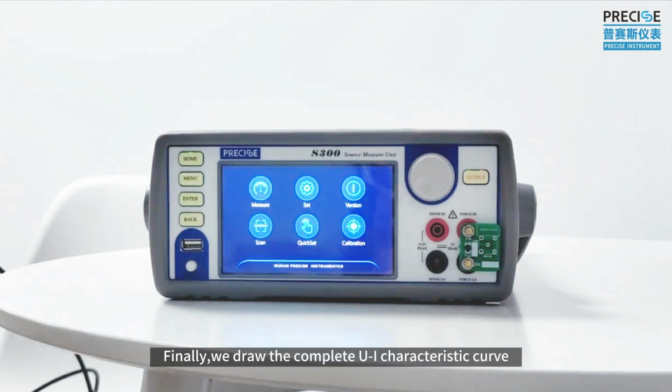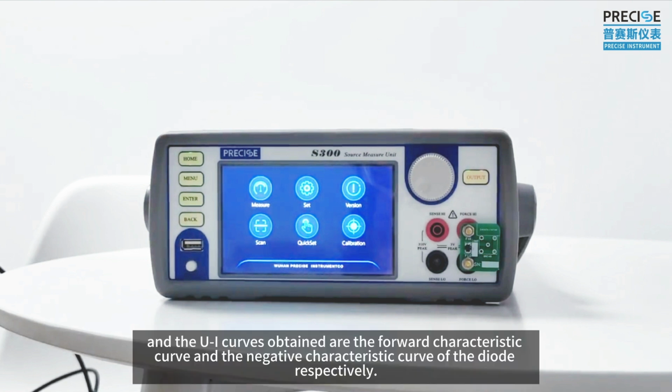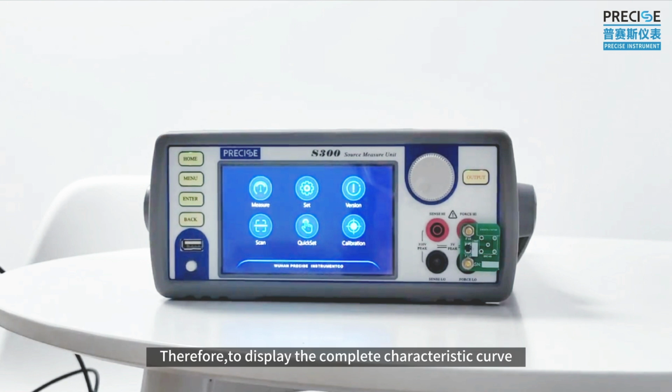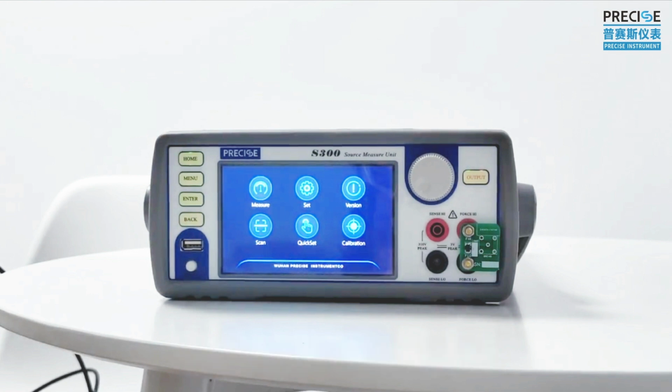Finally, we draw the complete UI characteristic curve. We tested the forward voltage and reverse breakdown voltage above, and the UI curves obtained are the forward characteristic curve and the reverse characteristic curve of the diode respectively. Therefore, to display the complete characteristic curve, we only need to merge the two measurement intervals above.